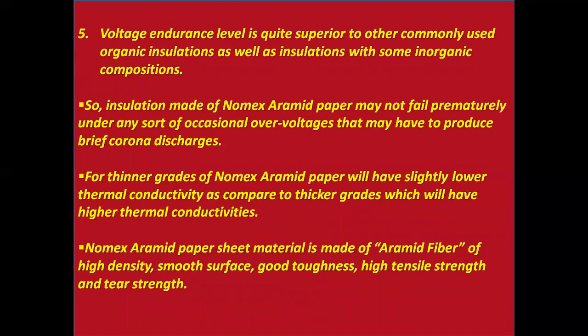Number 5, voltage endurance level is quite superior to other commonly used organic insulations as well as insulations with some inorganic compositions. So, insulation made of Nomex Aramid paper may not fail prematurely under any sort of occasional overvoltages that may produce brief corona discharges.